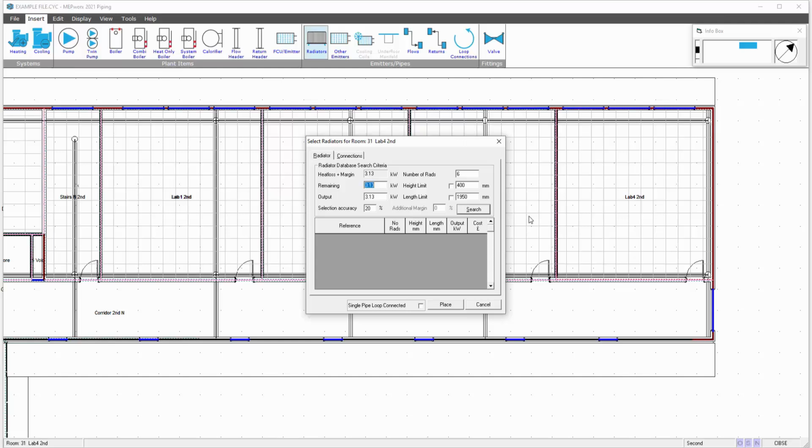And it automatically looks at the number of windows as a starting point from the model. Now in this case, this particular model was imported from Revit via GBXML. In plan form you can only see 3 windows. The reason it picks 6 windows is because we have openable sections in plan form. We don't want to be influenced by those, so I'm going to select 3 windows.